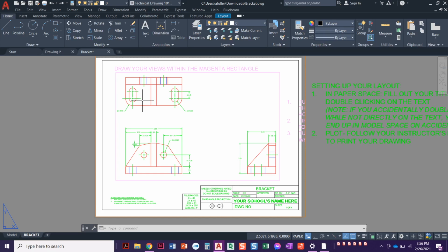They're so tiny, they've gotten so small I can't see them. It's not that the bricks are not actually there. It's not that the bricks are truly getting smaller and smaller. I know they're all the same size, but from my vantage point, from my viewport, that viewport scale has just gotten so far away that I can't see the brick pattern. And so that's what's happening. Once we come in here and start adjusting our viewport scale, the dashed lines are getting so far away that they're losing their clarity. They just look like a solid line.